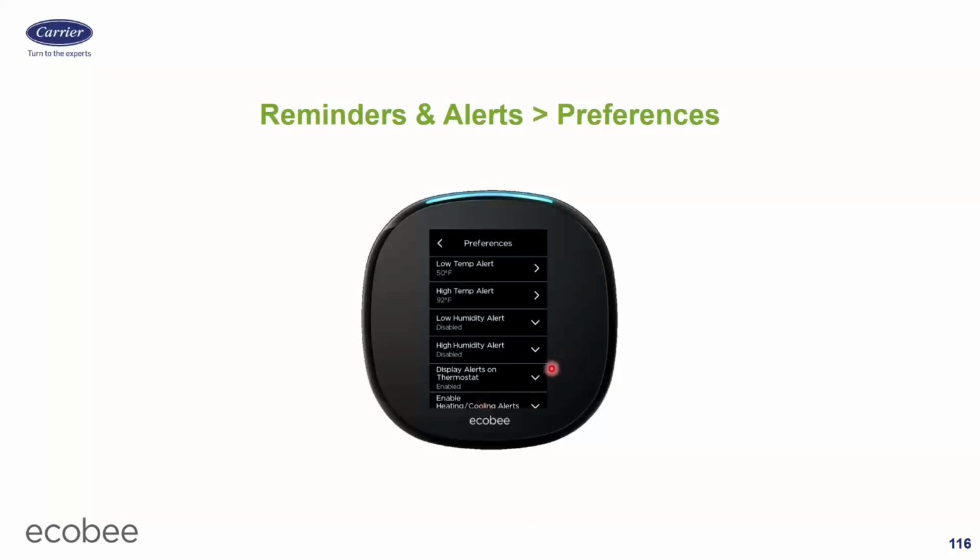Display the alerts on the thermostat. This is defaulted to enable, and I would leave that on normally. What this does is whenever there's an alarm that gets emailed out, it also shows up on the thermostat along with the contractor info. Usually you want that to happen. There are some times you want to turn it off. When do you want to turn it off?